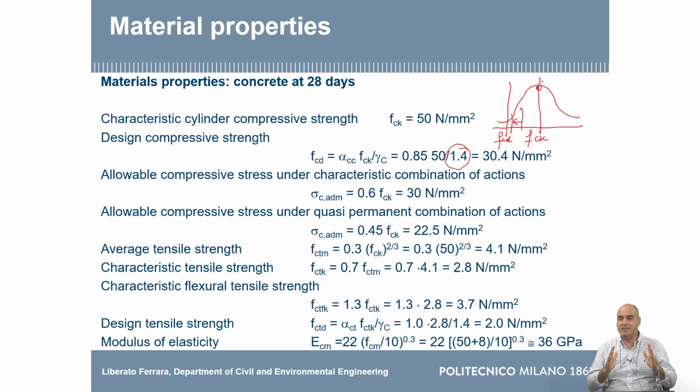Okay, direct tensile strength. If you want to experimentally measure it, you should make a prism of concrete, glue or grab it, and apply tensile force. Very, very difficult test, very unstable. You need very precise control. You need a very stiff machine and so on. But also